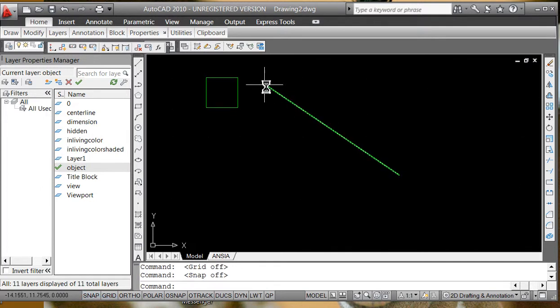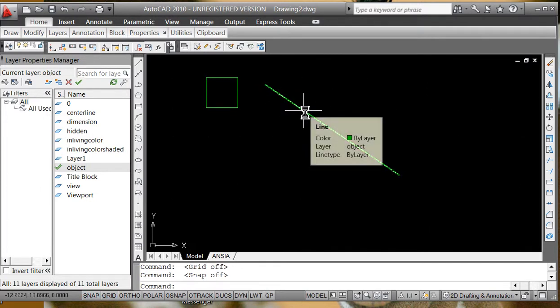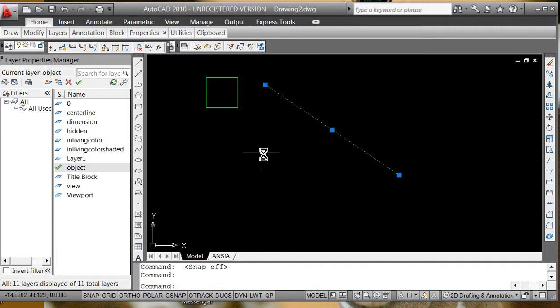I'm going to turn them off. I'm going to show you one more grip edit as we think about, first and foremost, learning the way the Windows world works, and then going back into what you're going to learn to do for drafting, which is to really think about starting with orthogonal lines using Euclid's precepts, making things offset so they're square and orthogonal, and using a lot of fillets and a couple of circles to do almost all of your drafting.